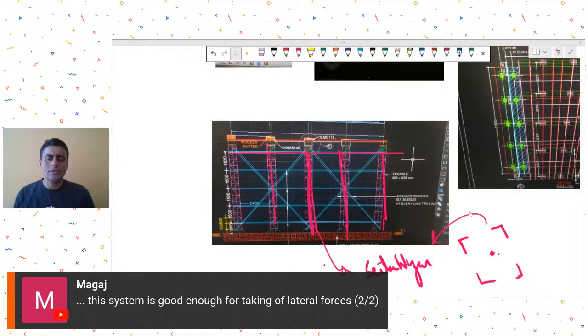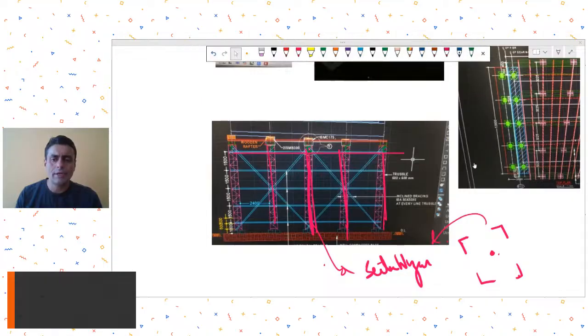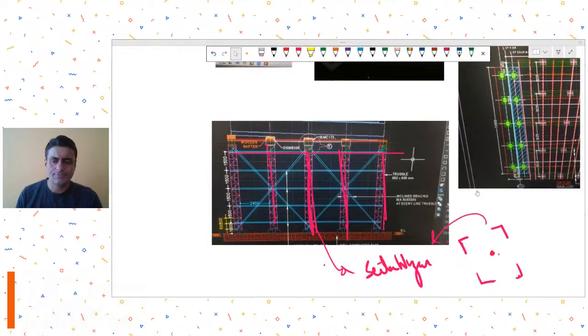Okay, so it has to see in most of the structures. If you see, for example, the case of WTC, World Trade Center, which is not there now, in that structure also it had closely spaced peripheral columns, and then it had a transfer system at first floor, I think, and then below that the column spacings increased. So then, of course, you will have to consider the system that you have provided below the transfer slab to be effective in taking the lateral loads.